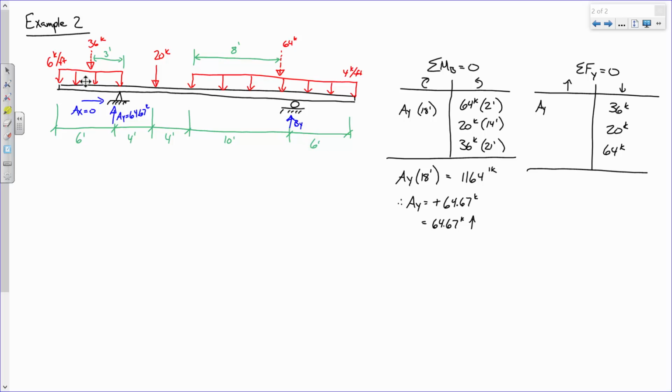We don't know that. The reason why is because you're making a point that on a cantilevered section you can have a significant moment. And so let me say this. It's very possible that given the distribution of moment you have an Mmax right here because you have a large cantilevered moment sticking out. But unless you can see into the future and see the distribution of shears and moments across the rest of the structure, you don't know.